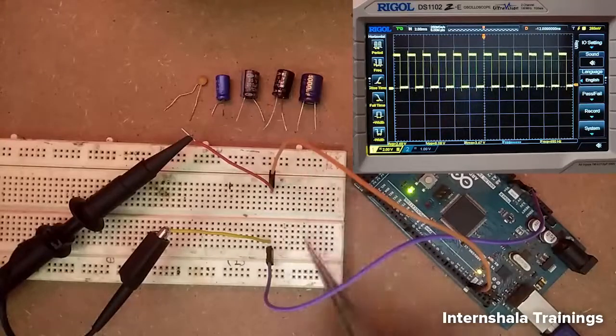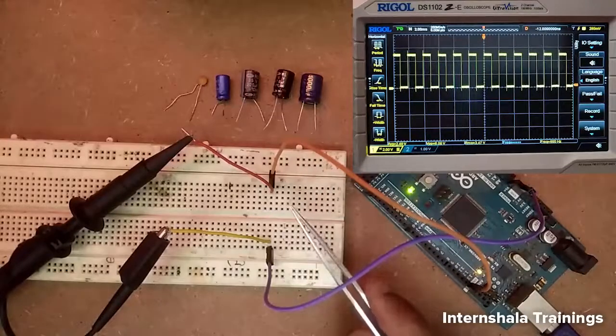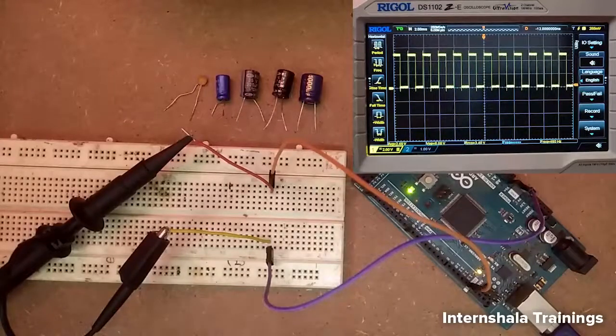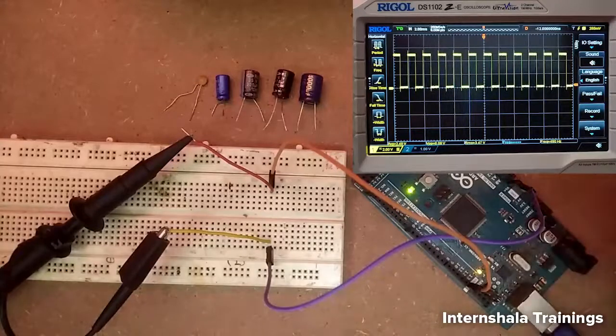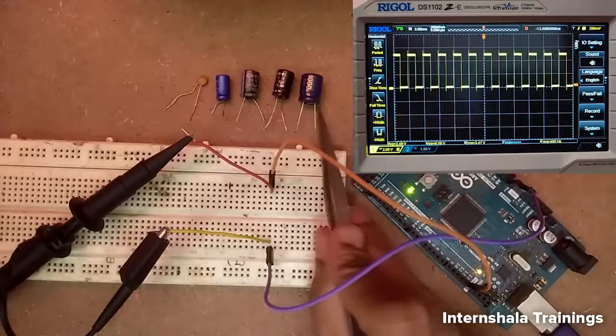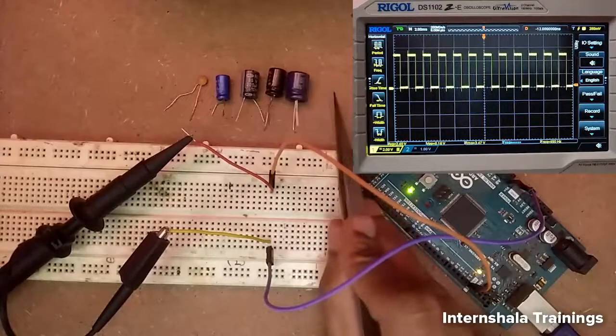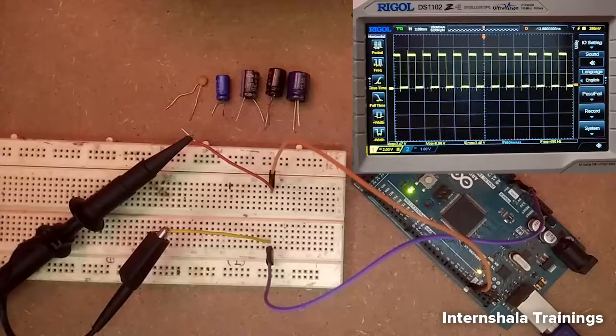And if you have to filter out a higher frequency, for example in megahertz, we discussed in the impedance versus frequency plot of the 100 nanofarad capacitor that it provides lower impedance at a frequency of 10 megahertz or somewhere around that. So whenever you have to filter out a higher frequency, you will have to go for lower values of capacitor, and whenever you have to filter out a lower frequency, you have to go for higher values of capacitor. This is a very important point, and it gives you an idea what range of capacitor you should choose to filter out a certain frequency.